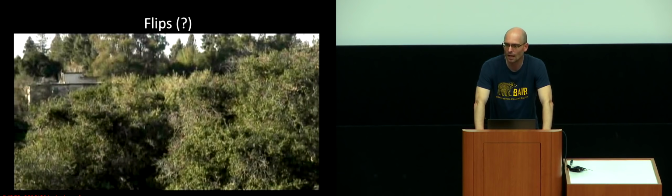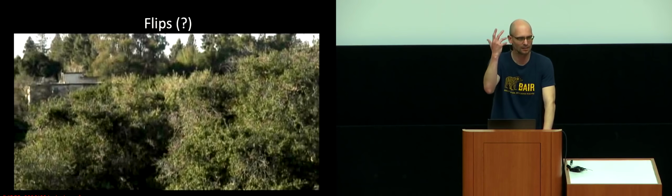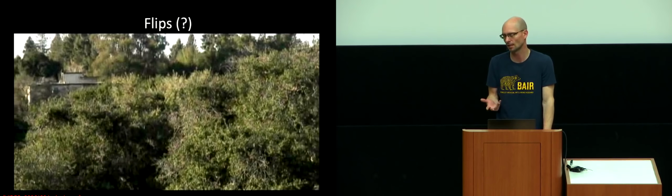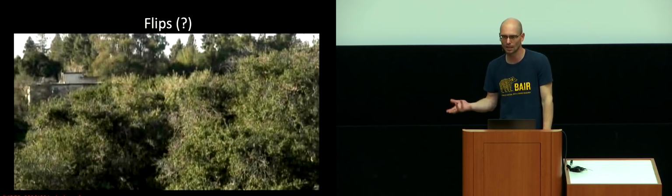So let's think about what happened here. So in simulation, this all worked out perfectly. But in the real world, it turned out it didn't work. What happened in the real world is we're trying to follow this path that we designed where the maximal reward is, and it had learned a control policy that's in simulation really good at following this path. But in the real world, this path was not dynamically feasible because the helicopter cannot fly any path. Only some paths are possible. And so we had asked it to fly a path that's not flyable. So it starts deviating from that path. As it deviates from that path, what it learned in the simulator becomes less and less relevant to the real world.